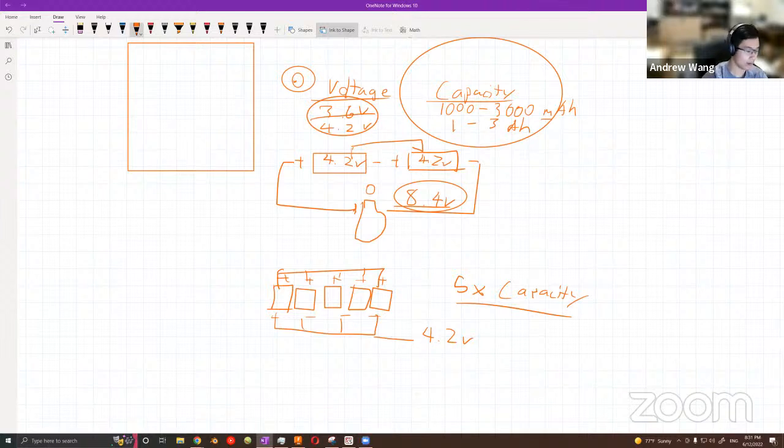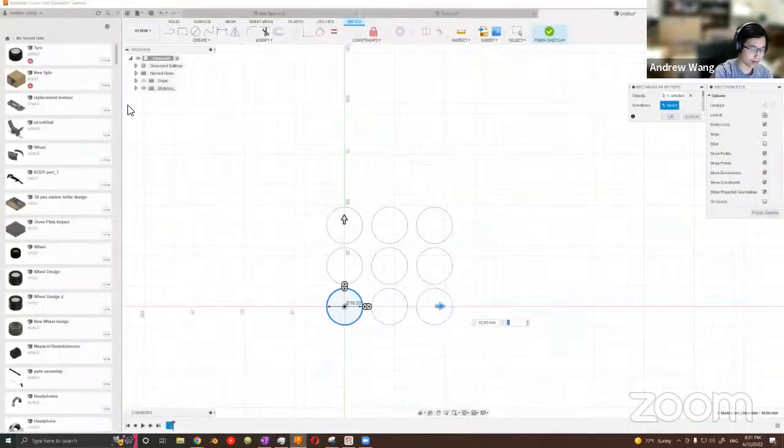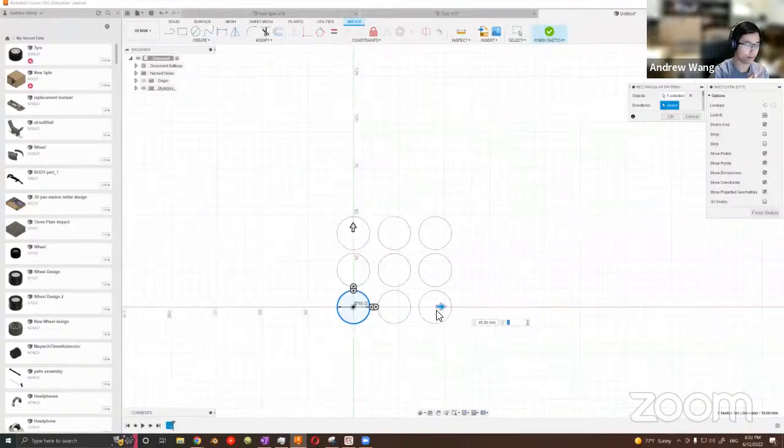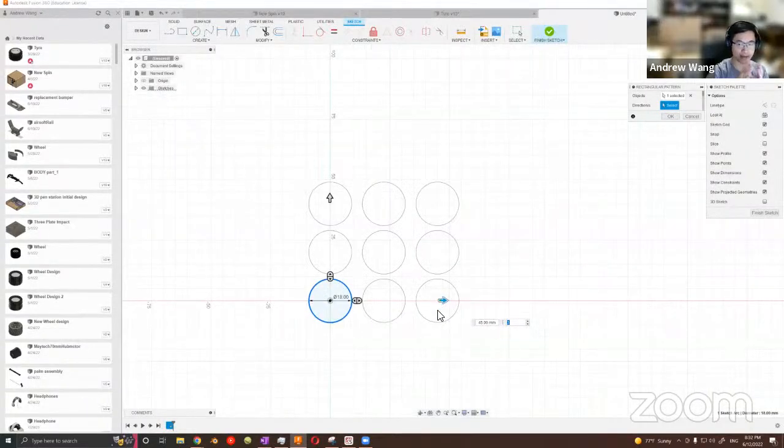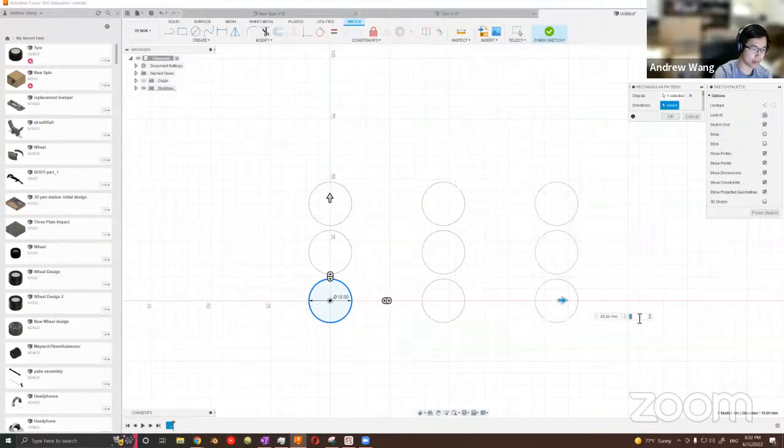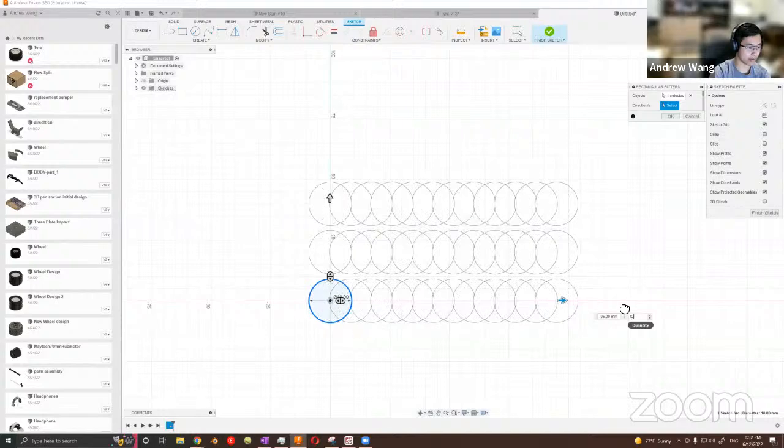All right, back from that tangent, let's go back to designing a battery. Our standard pack voltage is probably 48 volts. That's a pretty standard set for our voltage. We're going to have our pack go in series left or right, and then our parallel go up. Let's give it 12. 12 times 3 is 48 volts, like that.